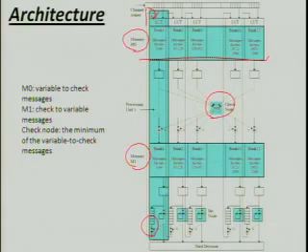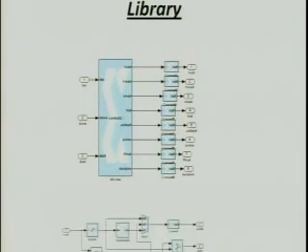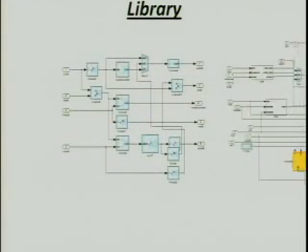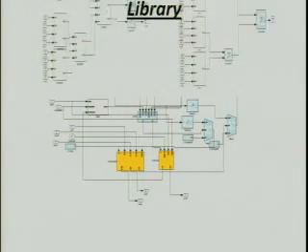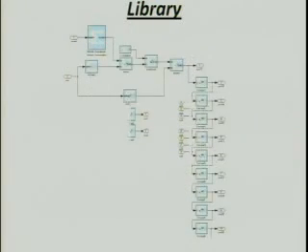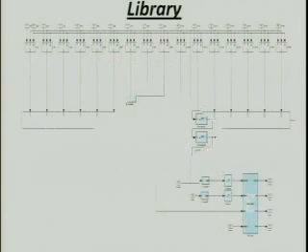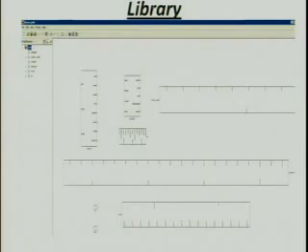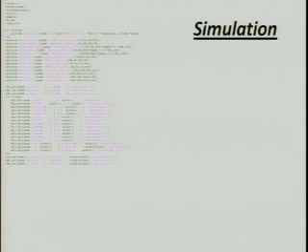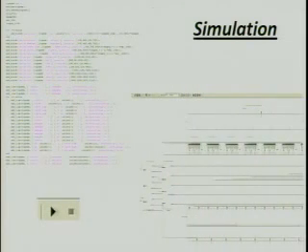After a general view of the decoding algorithm and architecture, I constructed the library that contains the processing blocks for building the decoder: the controller, the address generator, the processing unit, the check node, the noise generator, and the decision block. Then I configured the whole library. The next step, I wrote a Matlab script to construct the design using the blocks in the library. After I finish the script, I click on the simulate button. The whole design will be automatically constructed.